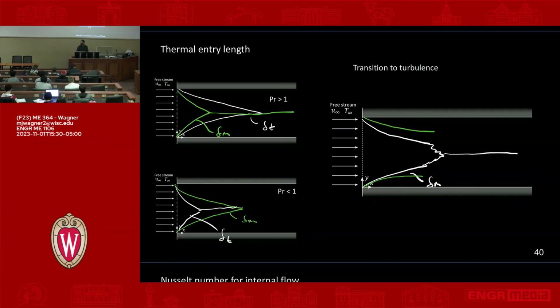Bulk movement of the fluid. And that is not dependent on the conductivity of the fluid or viscosity of the fluid. It's just the bulk movement, right? So the same thing is moving momentum and energy in both of those cases. So actually what happens is you get both of them growing together at the same point.